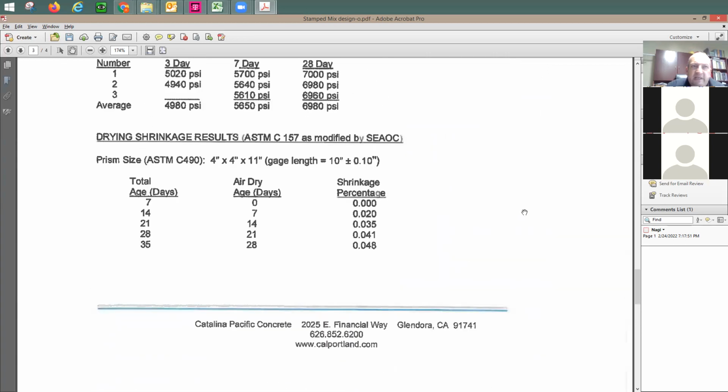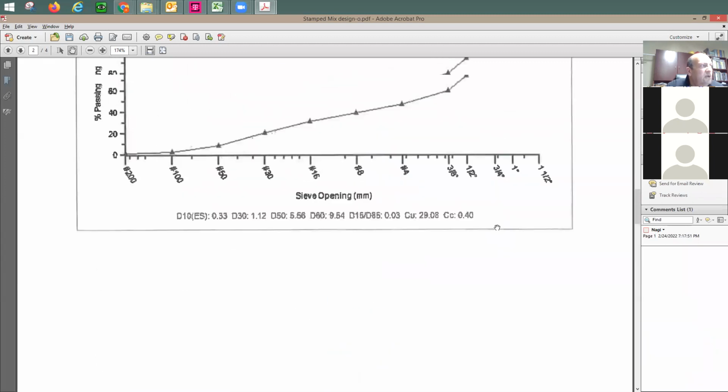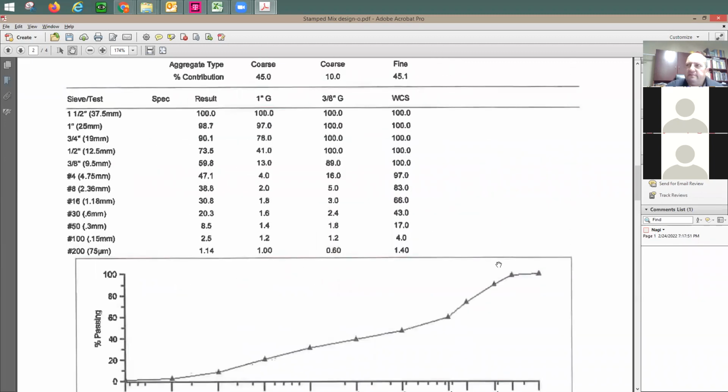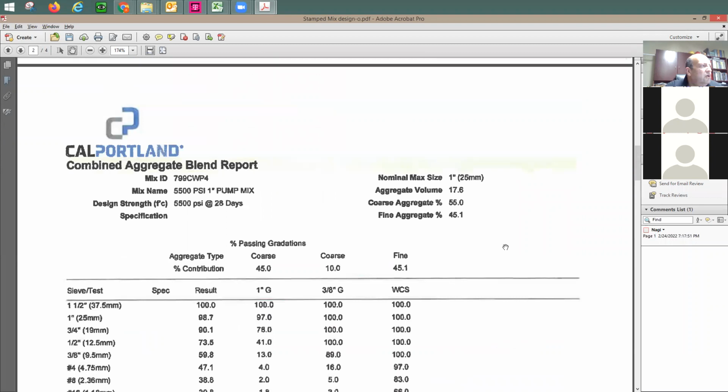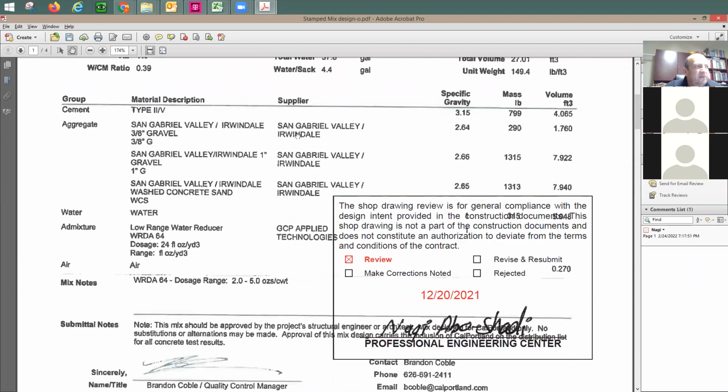So you don't really do any mix design these days because you have tons of this, unless all of a sudden we have a new aggregate supplier. Let's say that you move to some place where one of these aggregate suppliers doesn't have enough aggregate anymore, and you need to move to another mountain from which they bring the new aggregate. In a case like this, you need to restart something new. And you have the methods, you have the templates ready. You just figure out the specific gravity, and then they have some design values.